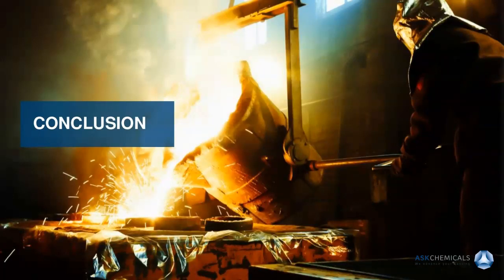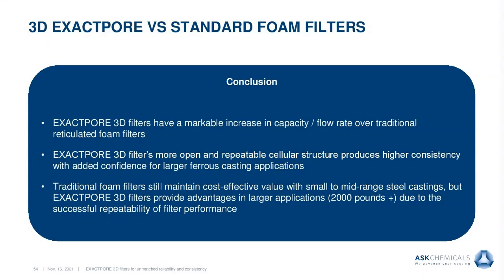To review some conclusions, 3D exact pour filters have a remarkable increase in capacity and flow over traditional reticulated foam filters. The exact pour 3D's more open and repeatable cellular structure produces higher consistency with added confidence for large ferrous casting applications. And though traditional foam filters still maintain a cost-effective value with small to mid-range steel castings, the exact pour 3D filters provide advantages in larger applications, which would be 2,000 pounds and higher, due to the successful repeatability of the filter's performance.